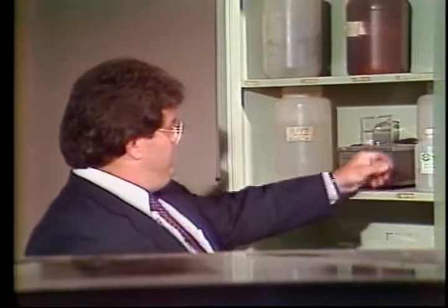Sometimes when there's a presence of soluble salts in freshwater systems, bentonite just doesn't act the way we want it to. See, the presence of soluble salts tends to reduce the hydrational capabilities of bentonite. So what may happen is we'll add more bentonite than actually required to get the viscosity we want. So what do we do?